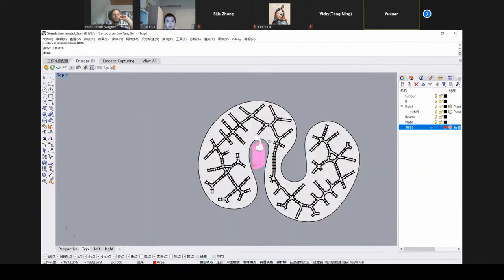I think arrange the beams on the ground may be more easy and also more practical for us, because when the roof is hung up, and has started deformation, it makes it more hard to control the accuracy. So we can place the platform on the ground, and we can place the platform around the roof and also in the center of these openings, so that we can reach every corner of this roof.